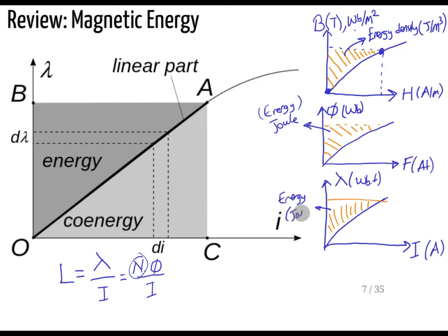And again that gives you the energy. That is joule. And actually, if you think about the slope of these curves, what is the slope of flux divided by current? This gives you the inductance, right? If that is a straight line, it is a linear system and your inductance stays constant, and if it starts saturating, the inductance is reducing as it gets excited.